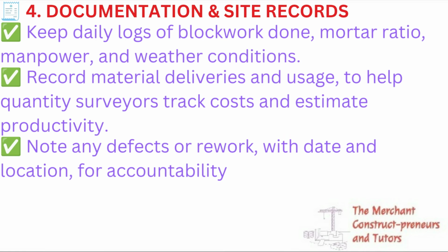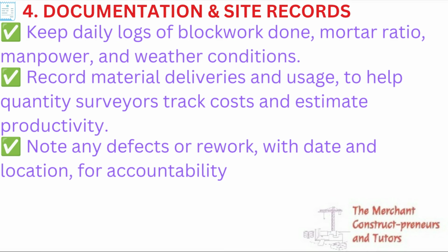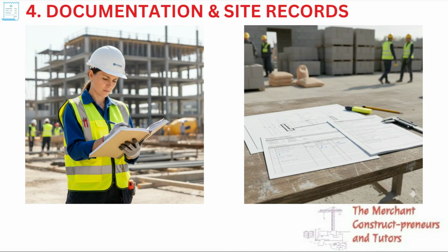And then if there is any defect in the work, you need to include it, write it down, record it, that this is what it is, so that once there are claims for delay or extra works, you can actually have a document to show when it happened and whatever has happened. If it rains and maybe the rain spoilt the job that has been done, it needs to be recorded and the date needs to be there.